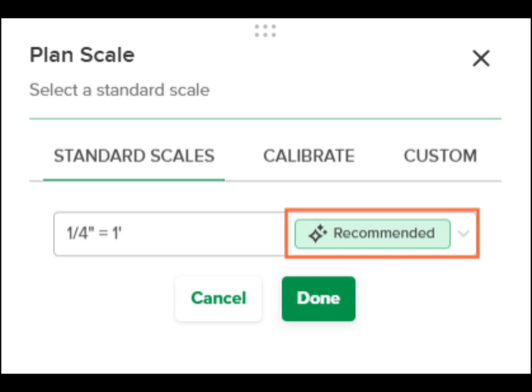Step 4. Scale measurement correctly. Scaling errors are one of the most common causes of wrong quantities. Always use the drawing scale bar, not the written scale. Verify the scale using at least 2 known dimensions. For piping, measure centerline lengths and keep fittings counted separately. Recheck the scale whenever the drawing revision changes.